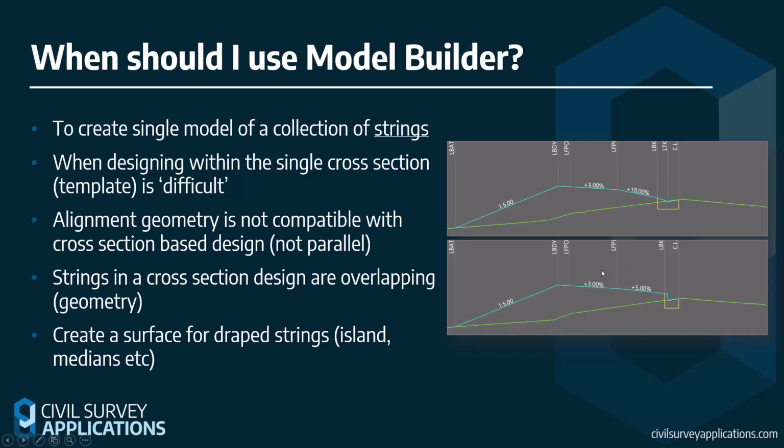Whereas with a Model Builder model, we could have this footpath designed completely separately and then have it connected back to the layback or the barrier curb as one single model, but actually having them designed independently of each other. We did a string code techniques webinar, which is available on our webinar playlist on our YouTube channel, which really unpacks in more detail how to design things separately and have them connected. And we're going to be touching on that today with the parking bays.